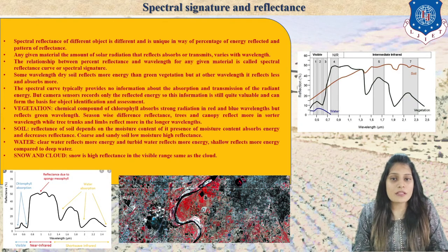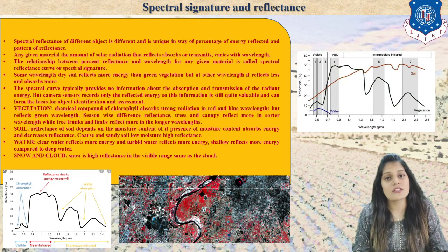Now students, look here, I have shown you the satellite image. Can you see all colors are properly indicating what it is? When you can see a red color, it means it is vegetation. When you can see a light blue color type, it is called urban areas. When you can see black dots or black color, it is water present in it, right? So this is just an example I am showing you of how the reflectance is in a satellite image. With the color combinations you can make it out, and with the colors we can work in the spectral resolution, right? So that is why it is known as the spectral reflectance curve, right?